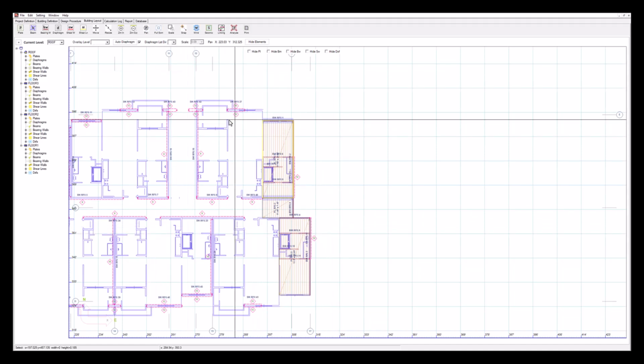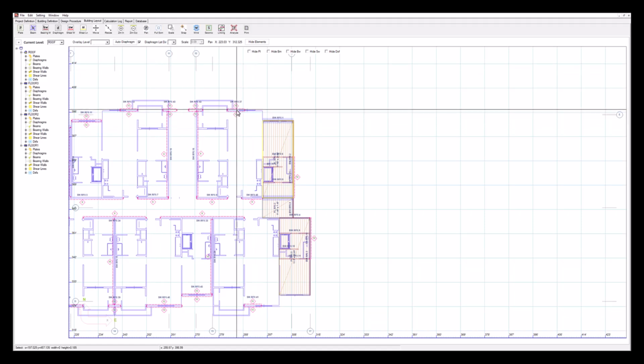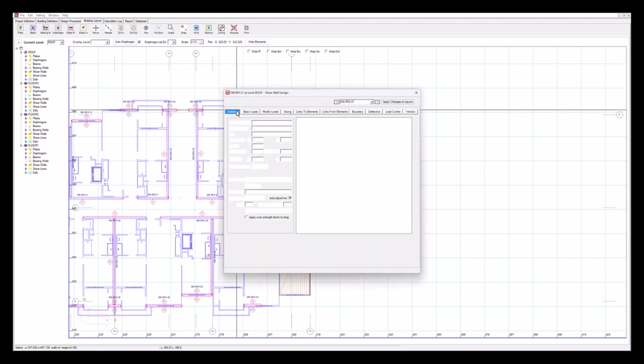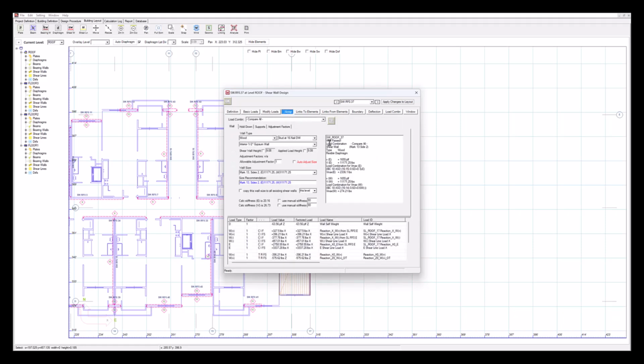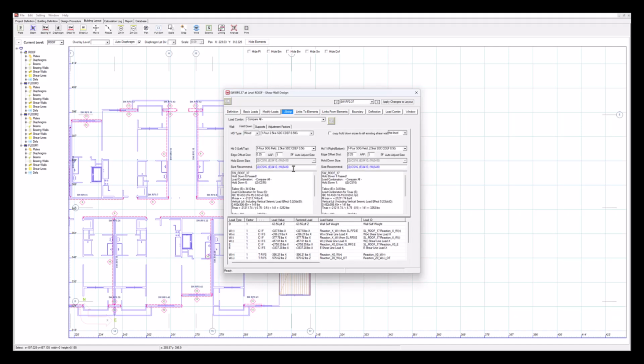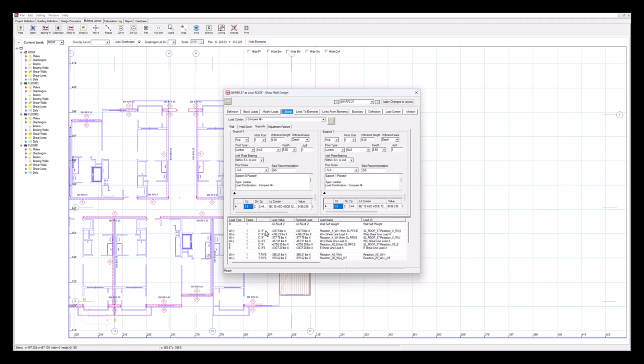The other piece is your shear walls. So your shear walls are going to be calculated automatically for you, and I'm going to double click a shear wall, and the sizing is determined for you, tells you that the wall has passed and that calculation has been done for you on that shear wall, carrying the forces from the lateral loads right in there, as well as calculating the hold down that will be required for it. So you'll see hold downs, and then the posts in that shear wall will also be checked for you.